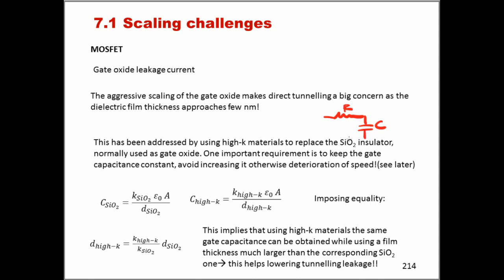So this RC circuit, as you probably know, immediately points us to the fact that in operating my gate stack, so in operating basically the capacitor that is on the gate, there is a charging and discharging process. It's not instantaneous, the operation of this capacitor. So there is always a time constant tau that is given by this, where R, remember, is resistance, for example, that could be related to the interconnecting wires that connect the gate of the transistor to the outside circuitry of whatever device the transistor is used for.